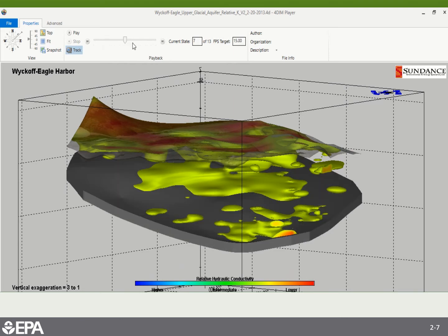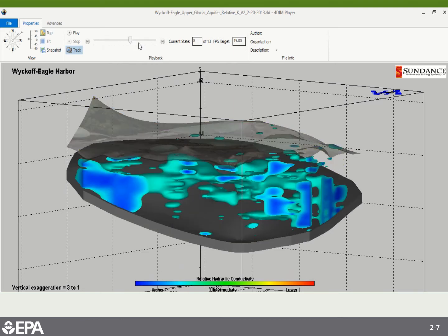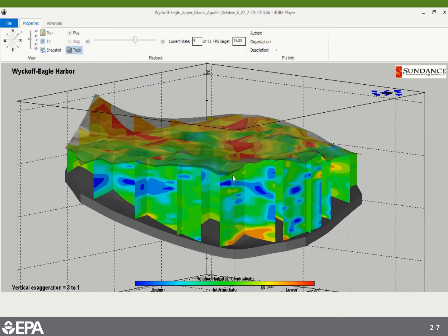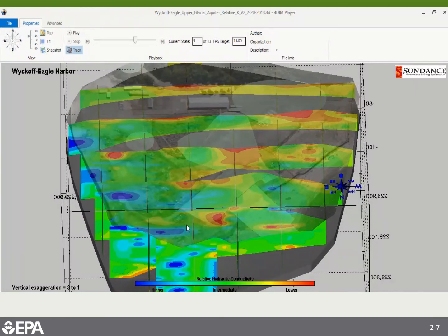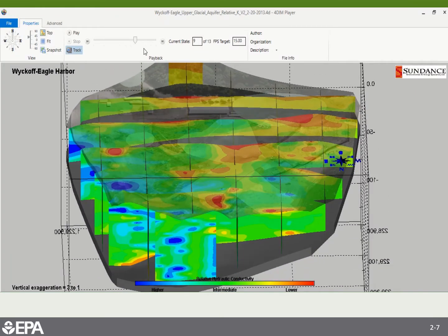And we can look at it a variety of ways. Here we've turned off the low hydraulic conductivity units, and we've included higher hydraulic conductivity units, particularly on this side of the site. And down close to the sheet pile wall as well, there are some gravels and other things. And of course we can do block diagrams and other ways to look at the distribution of grain size across the site with depth and slices across the site.